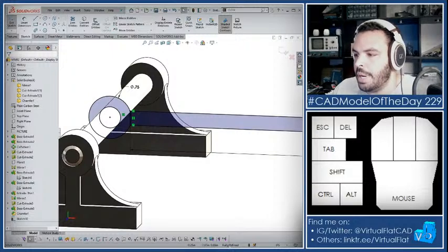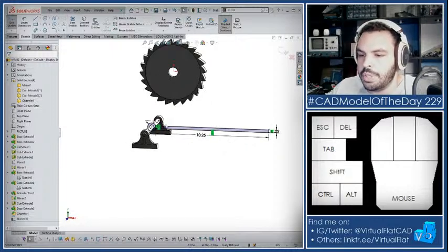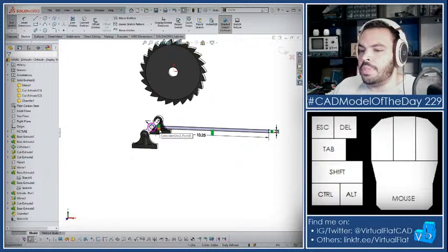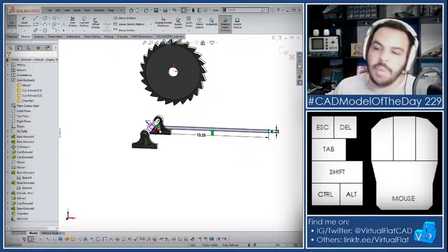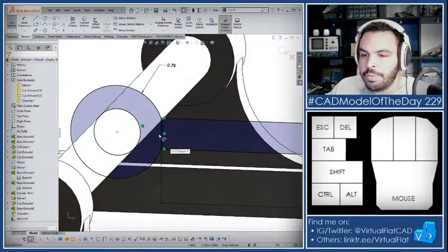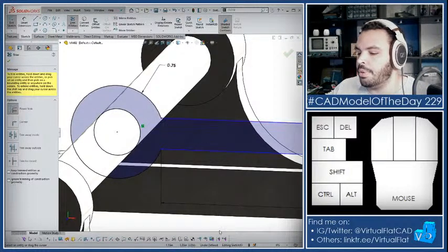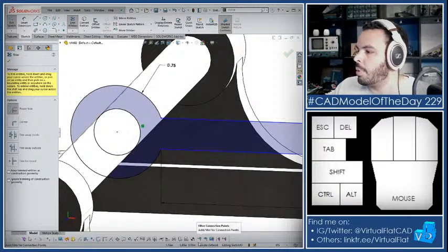If you look at the bottom of my SolidWorks screen, it says fully defined. All the material is black, which means every dimension that could be added has been added, so there's no dimension overlooked, which means you're not making any mistakes. This is good. It's fully defined right now, but I get my trim entities and I trim, and my lines are blue. It's underdefined again, so I have more work to do.